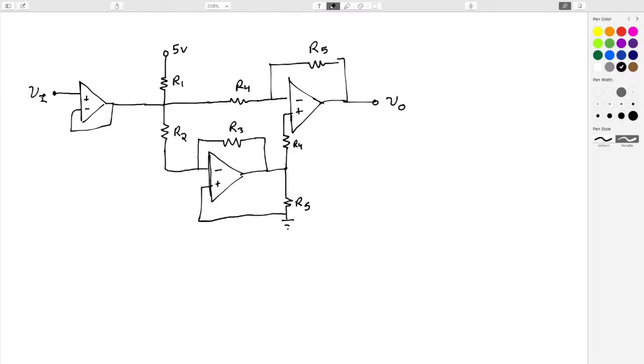So you could go up and put any arbitrary voltage in VI and then figure out what VO would be. The op amps as they're drawn, there's no power supply limitations. Nowhere was I told, nor do I see little lines coming up maybe saying like 3 volts. So we don't need to worry about the implications of power supply limitation. Instead we can just focus on how would I solve this.